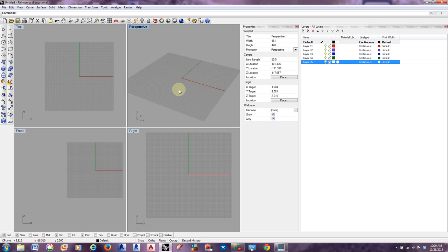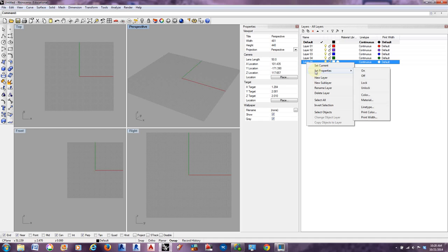If you have an object selected and you left click on a layer, you can put that object on a specific layer. That really helps with the workflow of the software. If you create an object that has 5 or 6 different parts that all come together, it's nice to put the different parts on different layers so you can turn them on and off.